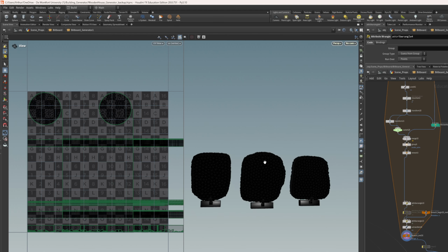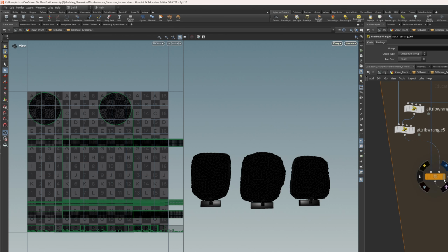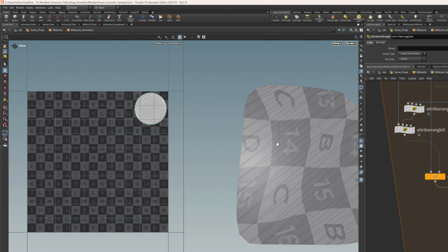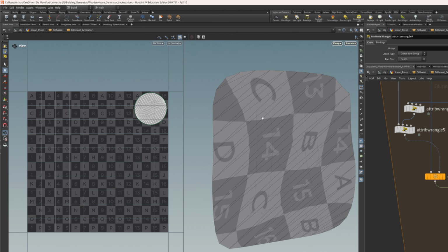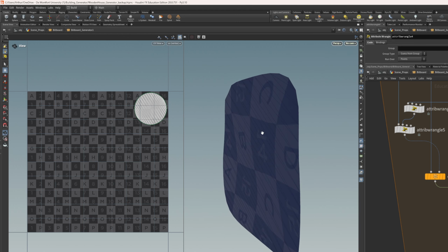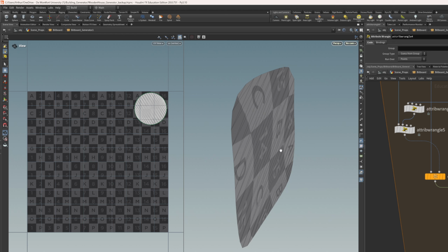Okay, so depending on the shape, there would sometimes be instances where, and I'm not sure why it isn't doing it now, your lines here would end up overlapping, and then you would end up having normals facing this way, and then the extrude that is powered by those normals would end up having the faces come forward and backwards, and then everything that worked off of that shape just got broken.